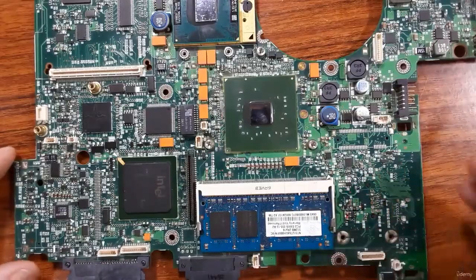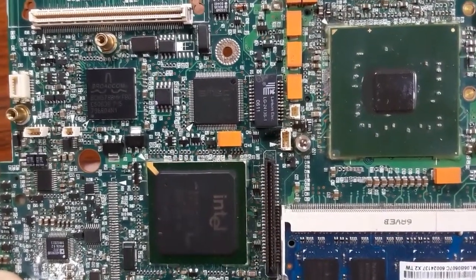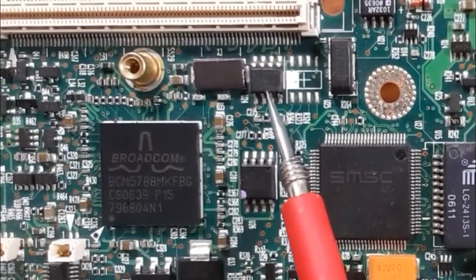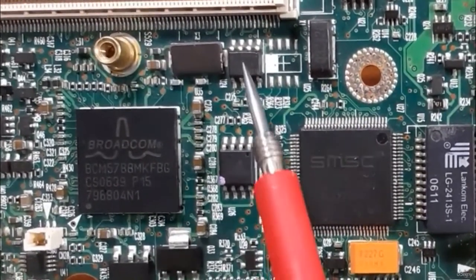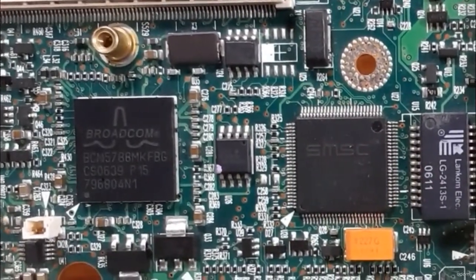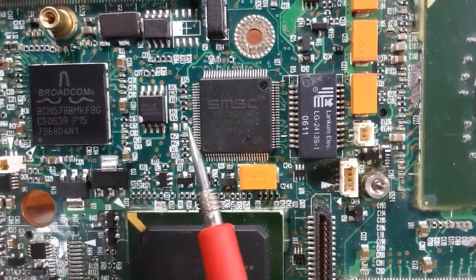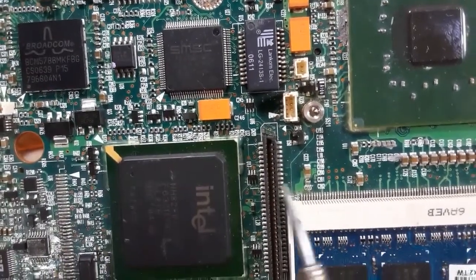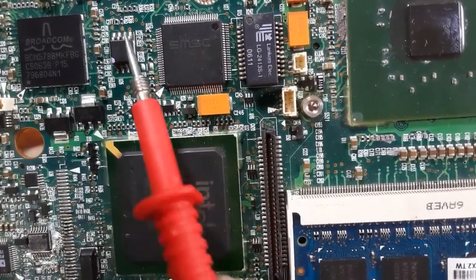Okay, so let's look for the BIOS. As you can see, here we have the ICH, here we have the Super IO, and here we have the BIOS. So this is a MOSFET or a simple IC, and this is the BIOS. Always the BIOS is bigger than MOSFETs and other ICs with 8 pins. Okay, so as you can see here, we have a color here. This color means the BIOS. Okay, so here we have the 3 components next to each other.